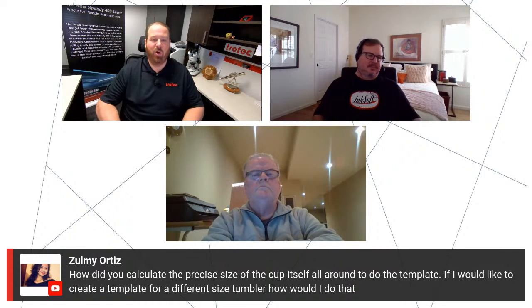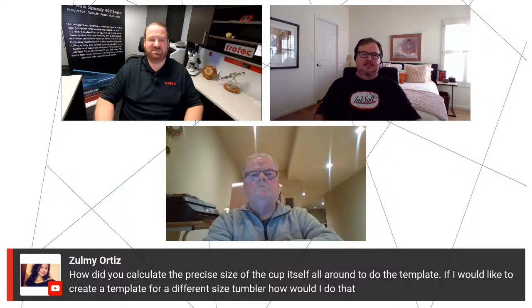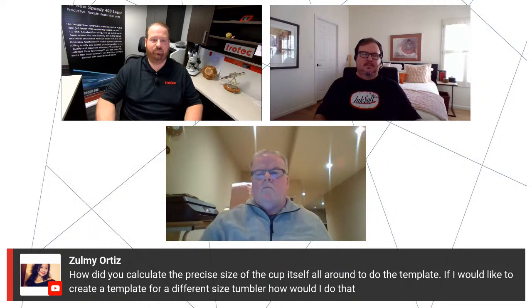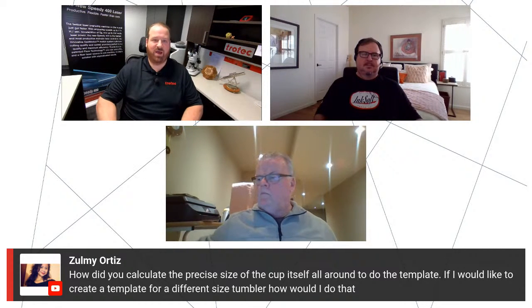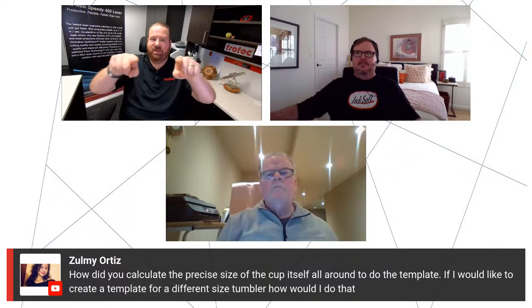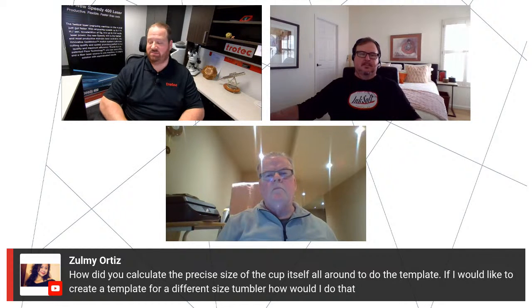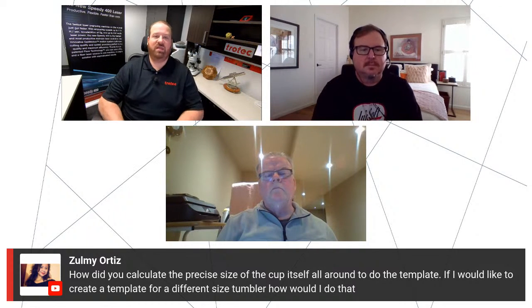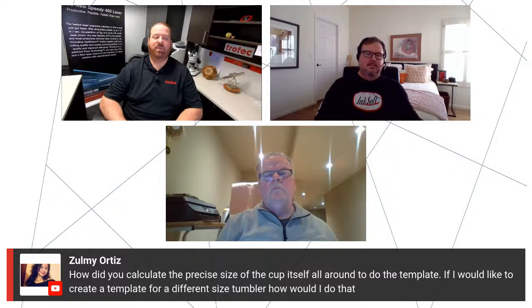If you're just doing something like a logo on it, you don't want to engrave more than about 1/3 of the front of that, so that you don't have to rotate the glass to see your graphic. But it is a good way to represent a product. The way that I will do it is I will draw it. I will measure the top, I will measure the bottom, and then I will draw kind of in between, so you have that taper effect of a cup on the screen that matches it as though you were looking at it from a straight two-dimensional plane. And then of course, if you're doing 3D, that's 360 degrees, it's a little different, but that's typically how I will do that, so that we can see what it looks like on the front.